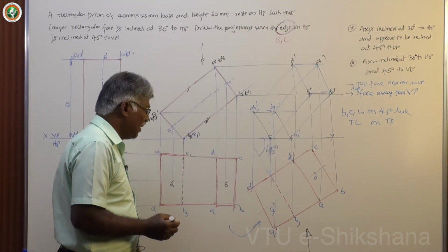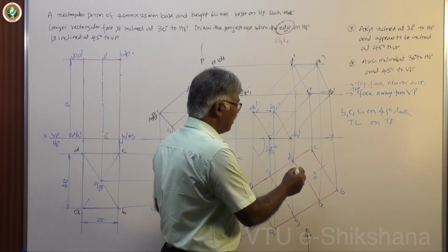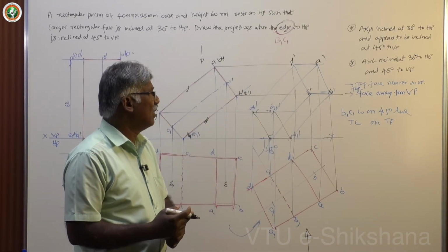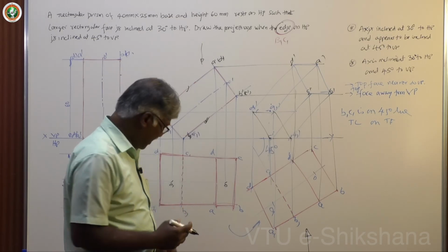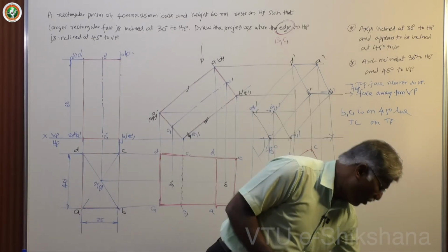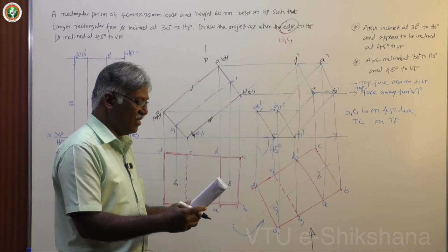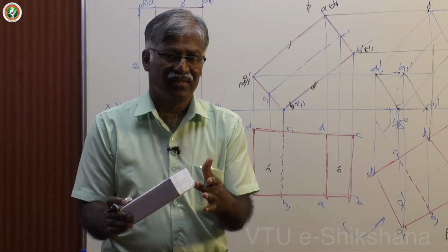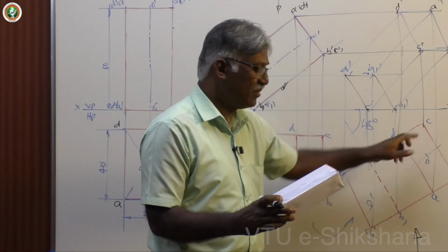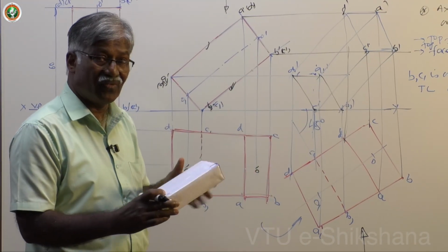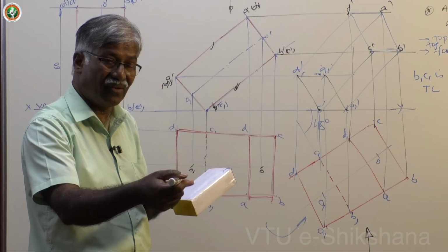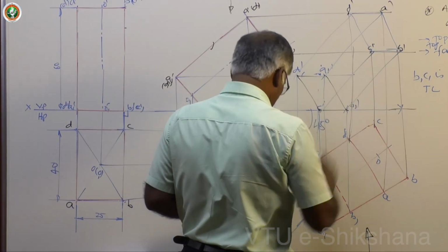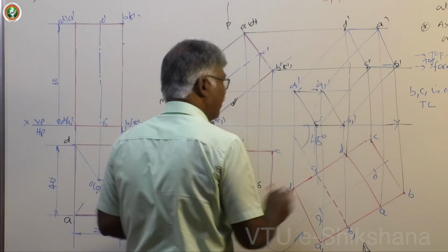Next, this is very interesting. You can use either farthest point method or the key surface method. Again, let me use this model. First position, second position, third position. See, here nearest surface is this. See, here this point is close to VP. That is farthest away, farthest point from observer. So that is not visible. Okay. Now analyze like this. This is not visible. Fine.